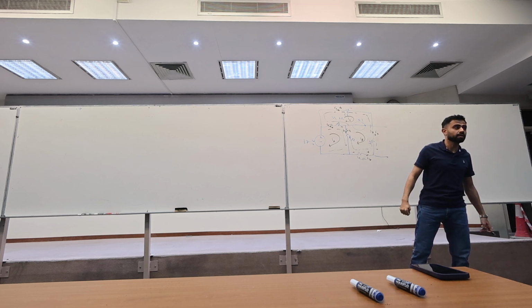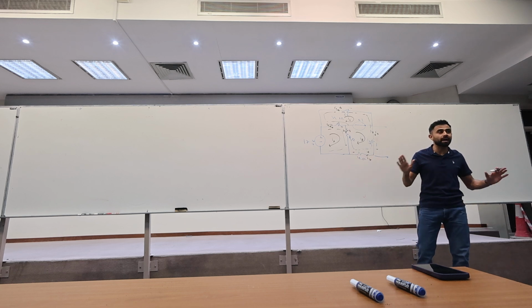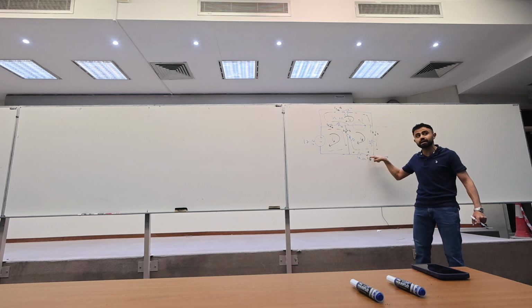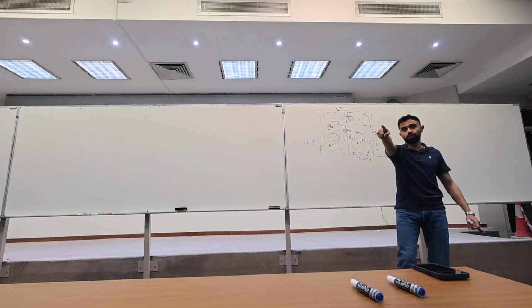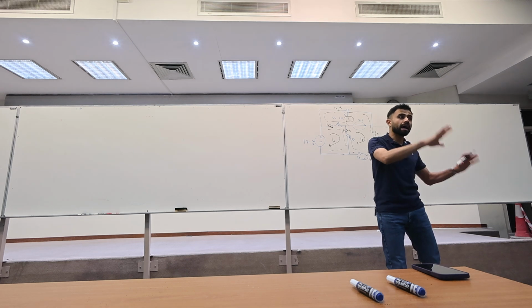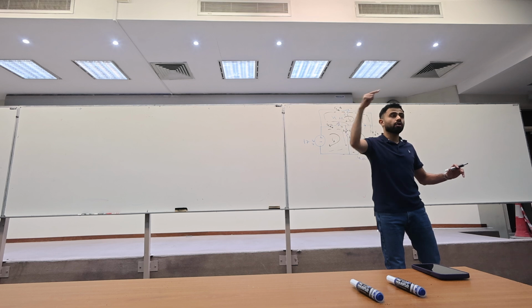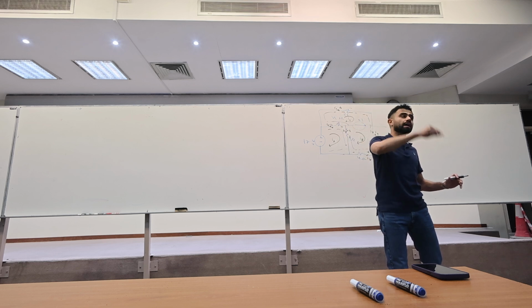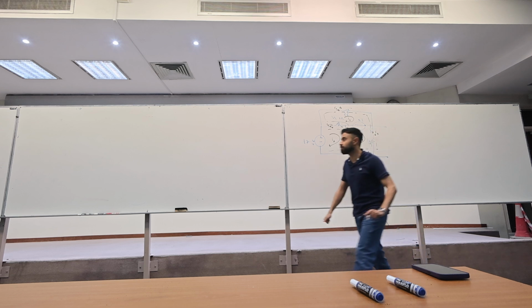If you want to put plus minus or plus minus, it doesn't matter as long as you define the currents properly. If it happens, like the quiz for section 2, homework problem 8, that the current enters through a negative, do not forget the passive sign configuration.